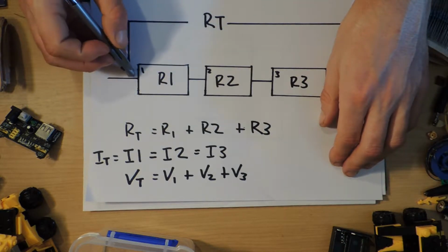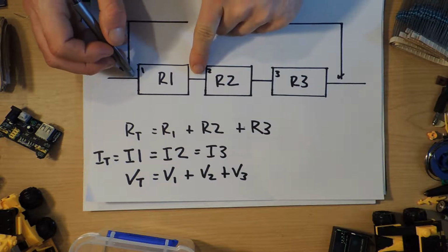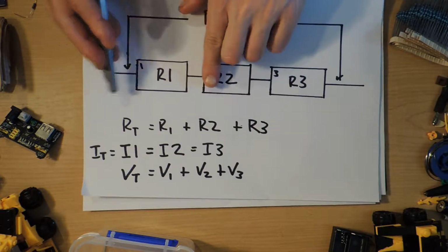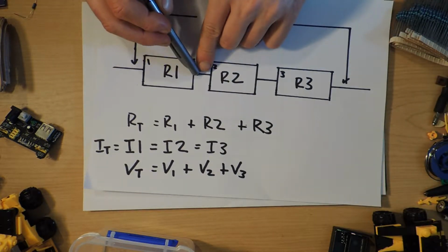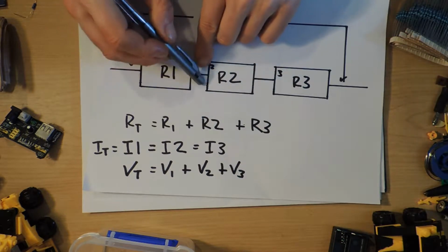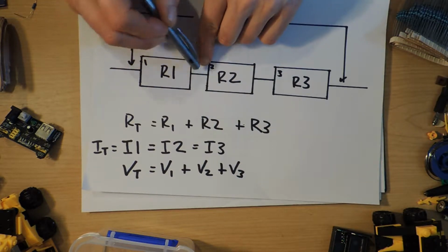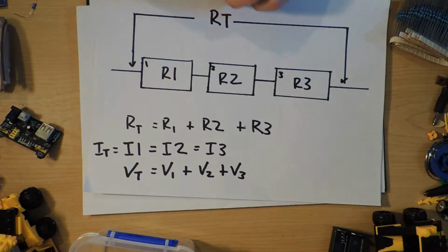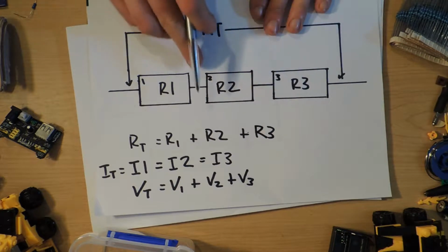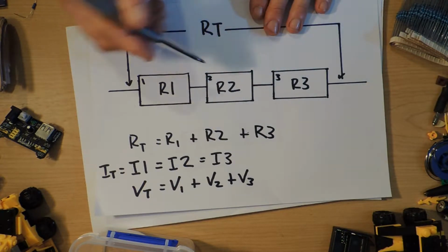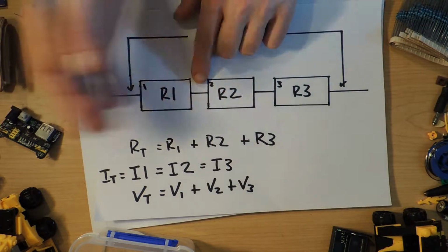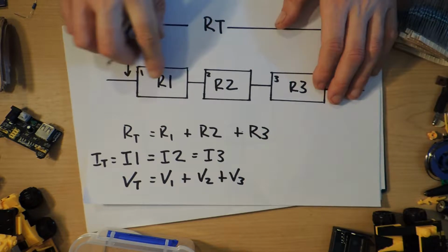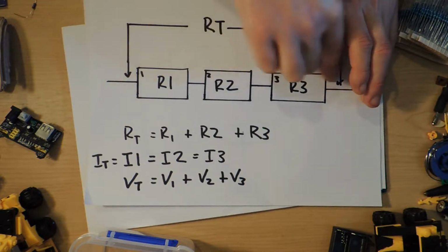So you might remember what I said a long time ago in my resistor rambles, that the current doesn't bunch up in little bits. So you can't have more current going through here and then less current going through here, because then some of that current would start to pile up at this region here, because they're waiting to go through this bit. So if 10 went through here but only 5 went through there, then you've got 5 sitting around doing nothing. And then you've got another 10 coming along, because it's continually flowing, piling up, and it just gets worse and worse and worse. So what happens is that the current is the same all the way through in a series circuit.